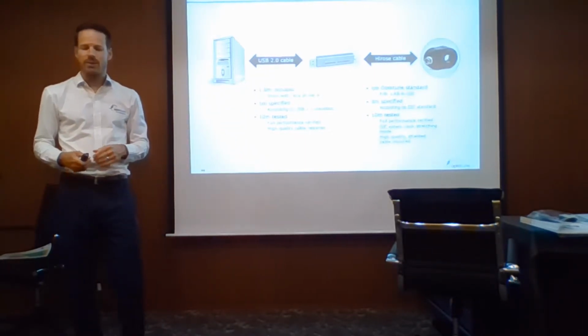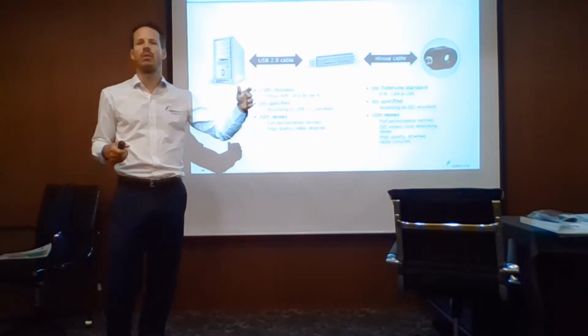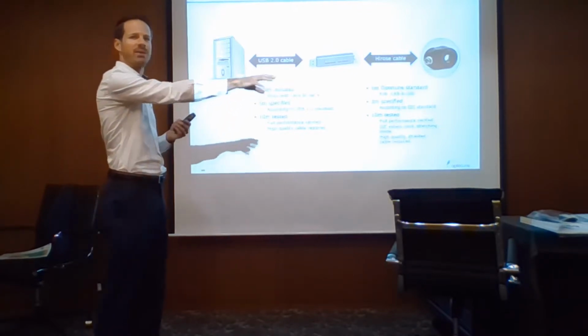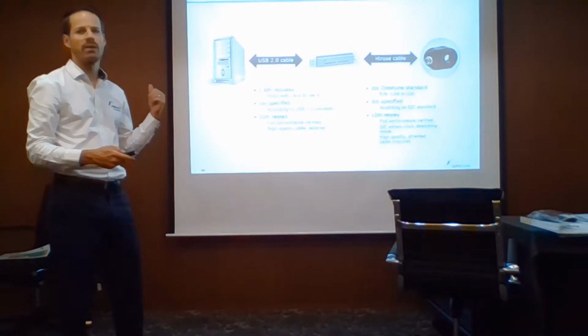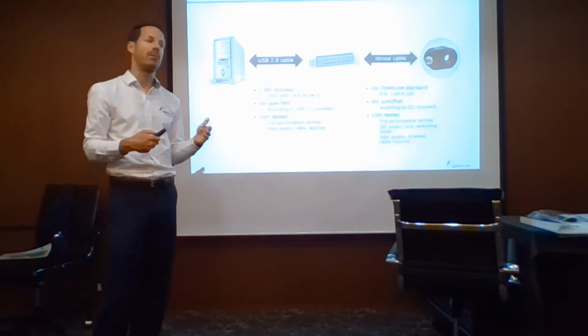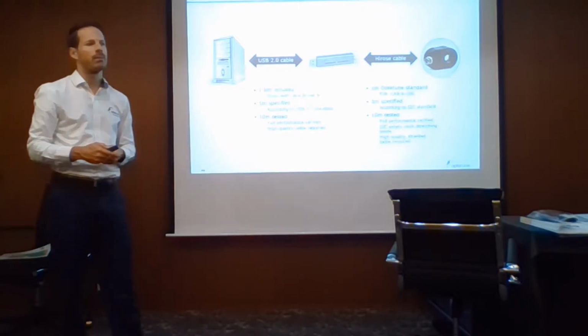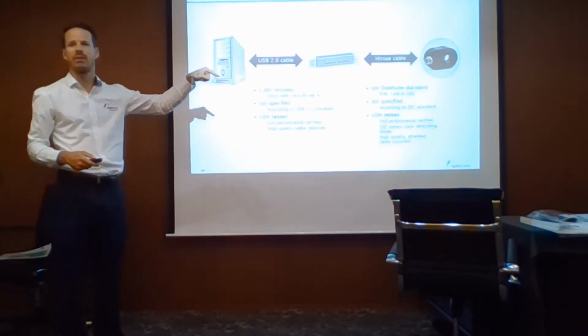But if somebody needs very long cables, maybe for traffic applications or for tunnel TV, something that goes in the tunnels, then it's better to work with the Gardasoft driver and use an Ethernet cable, because then you can easily go 100 meters of length. But then you need to have a power supply at the driver side.